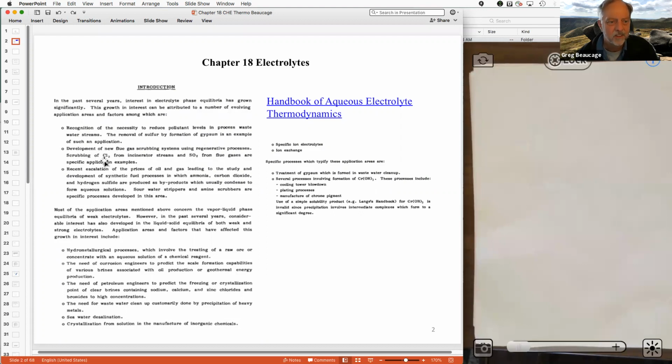Scrubber for Cl2. If you're going through processes where we're working with salts like titania, production of TiO2 is one that I know of. You start with TiCl4 and you end up with Cl2 gas. So you have to separate it with water, or you neutralize it with an NaOH solution. So it's all electrolytes, right? It's quite complicated compared to the normal chemical reactions you look at. Immediately you walk into a chemical plant and you're going to be faced with these things that you haven't been trained in, right? So it's fairly important to get an idea about this stuff.